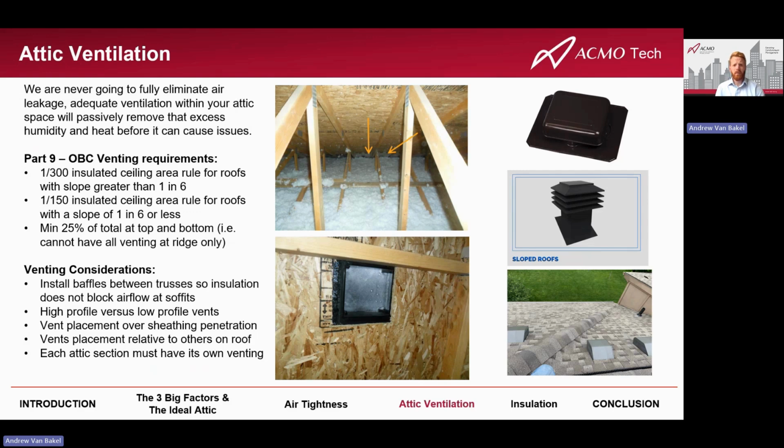And don't place it near a bunch of other vents, because short circuiting can happen, where air just as it exhausts out, it kicks around and comes right back in. And each section of the attic in between firewalls would have to have its own venting.